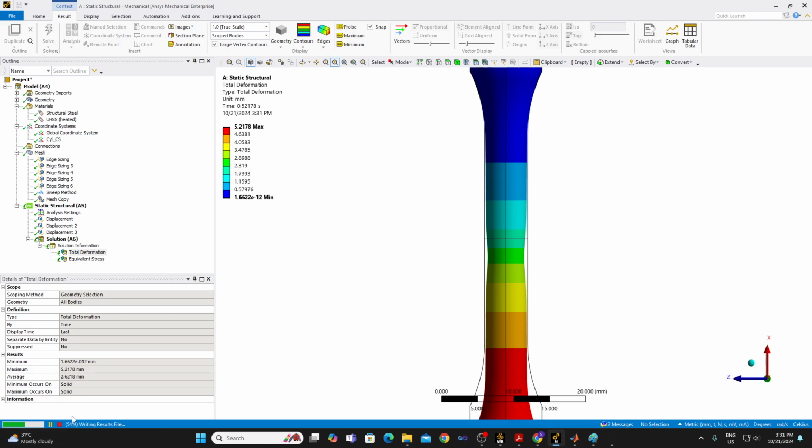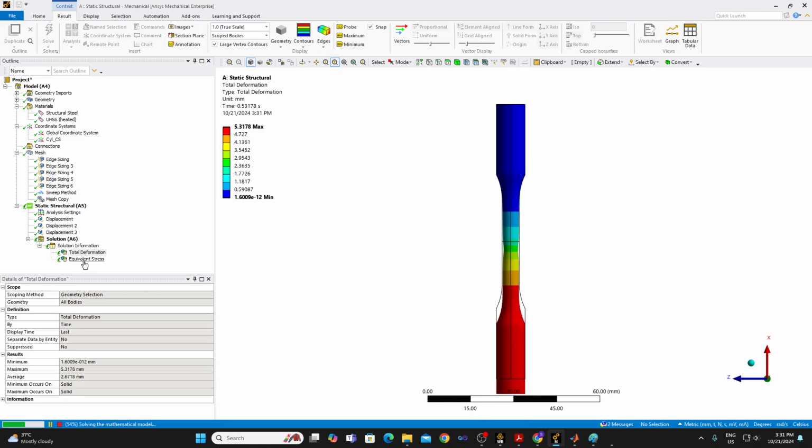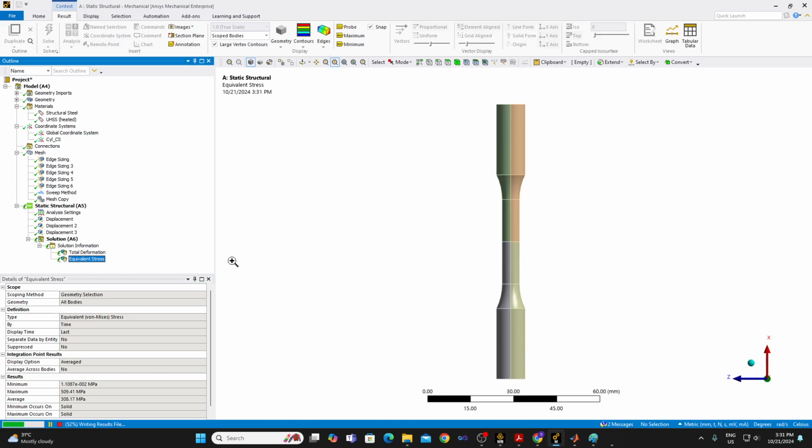Okay, the solution completes around 53-54%, and if you look at the stress value, remember 209 was the yield stress. We have already reached this much stress. Now remember, this is only the stress in the neck. Okay, and that is about 510 megapascal to 450 megapascal. But if you multiply that with the cross section area of the neck, that is not a huge force value.